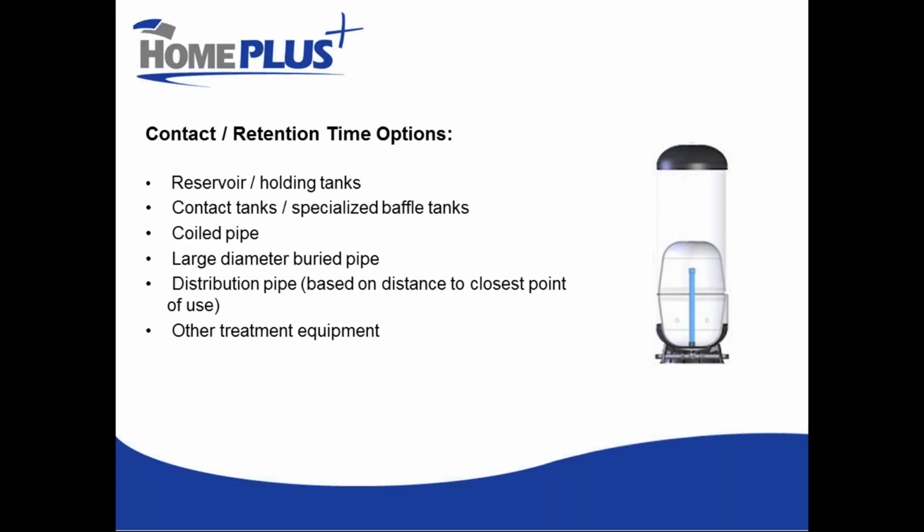Basically, anything that holds water between the chlorine injection point, or maybe best defined where it's achieved at least some level of mixing, and your first point of use on your distribution network. Anywhere in between, we can achieve contact time.